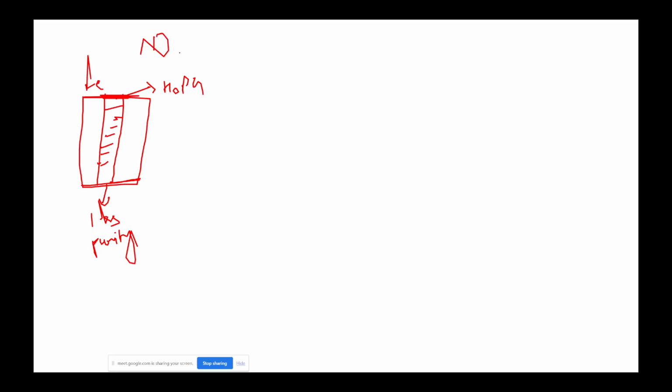So how will you manufacture this? First, you will get needle coke, and as I discussed a few slides back, you have to mix it with some pitch, or you can add some resin as a binder, and then expose this to more than 2600 degrees and go for the heat treatment process.